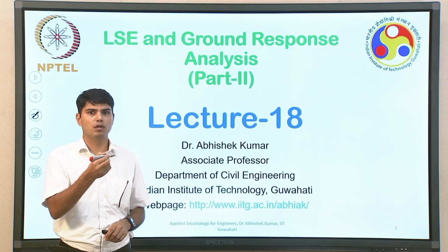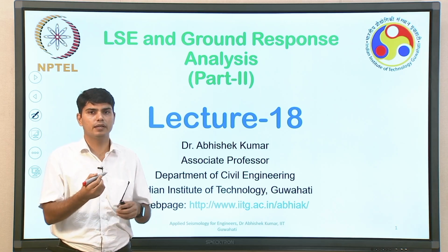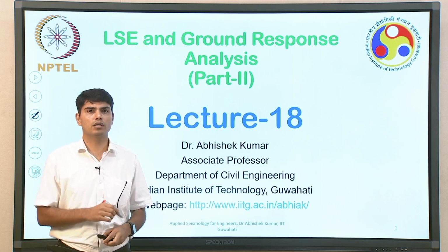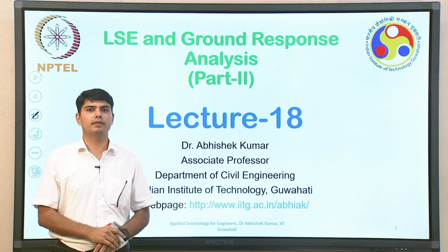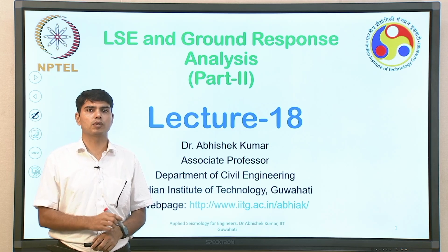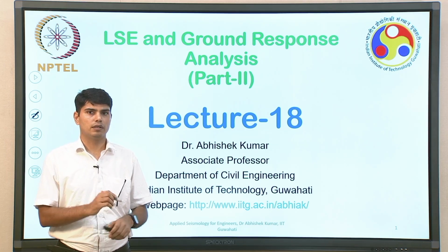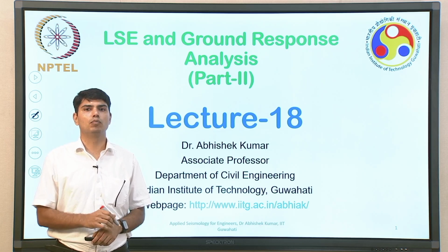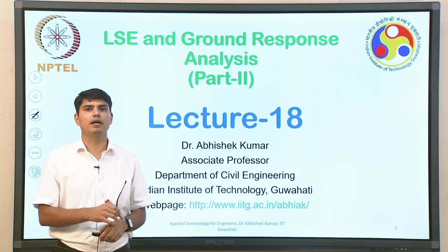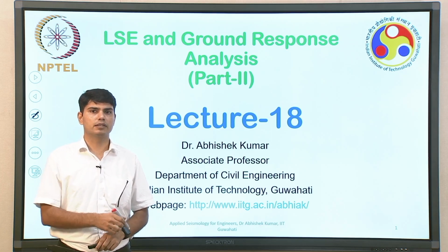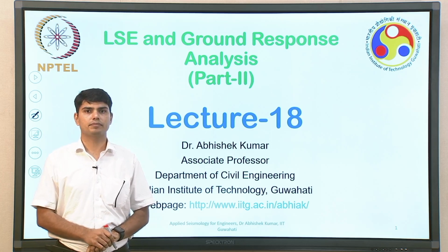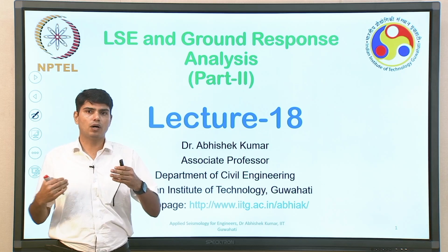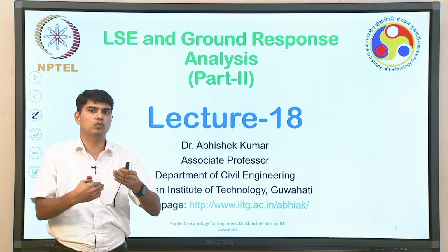whether the particular motion, ground motion signature can be directly taken into account for doing ground response analysis, or the motion which has been provided, whether it is corresponding to regional records, whether it is synthetically generated motion or motion adopted from other region having similar seismic activity as that of the site of interest. Once a motion has been selected, because it is how the soil layers are going to respond to that particular